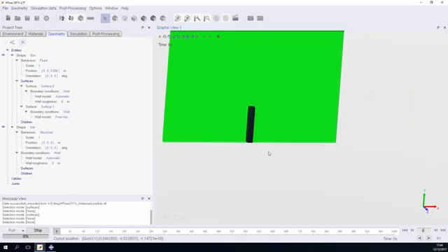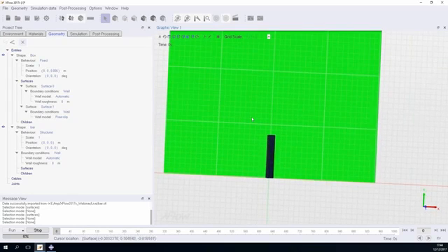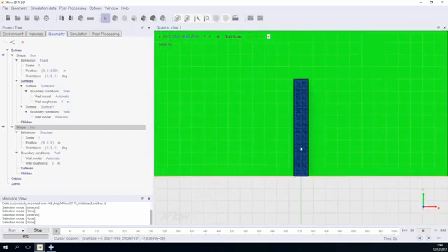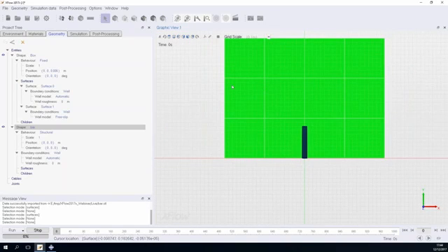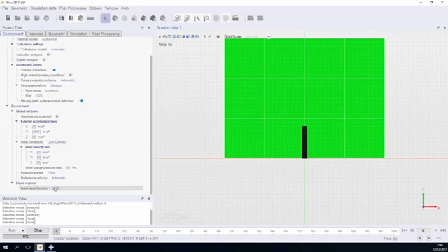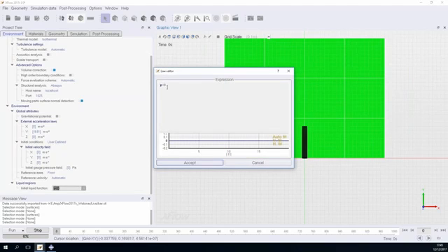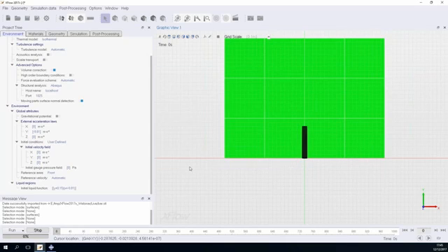Okay. And then I'm going to specify an initial height for my liquid. As you can remember from the video, we had some height of water that then collapses and crashes into the bar. So I'm going to specify that in here, and I'm going to use a Boolean function. That's another powerful thing of XFlow: you can specify a function directly in the function viewer and use that in the simulation. So that's going to be a Boolean between X and Y. I'm just filling up the left-hand side of my box. Perfect. So that is done.